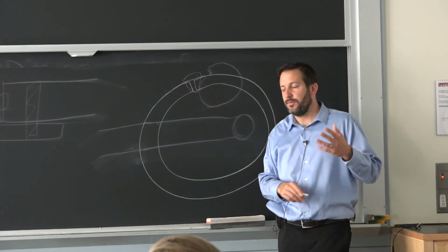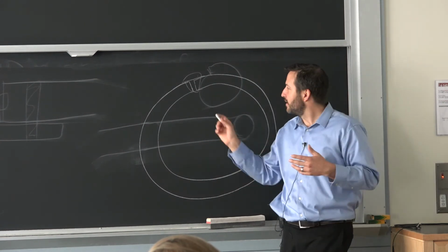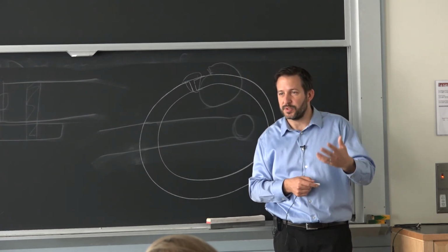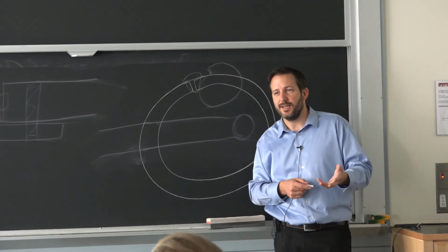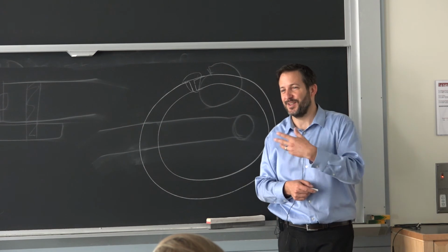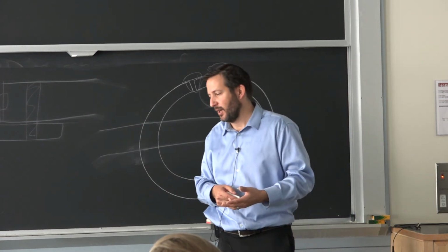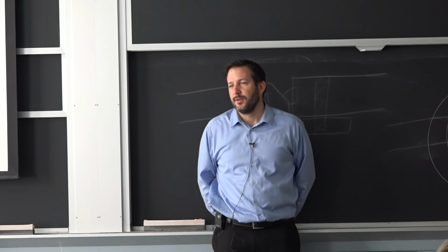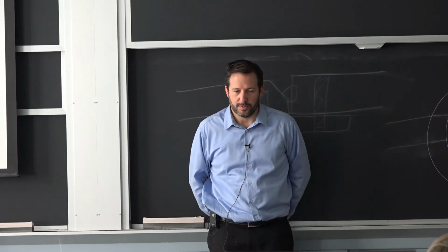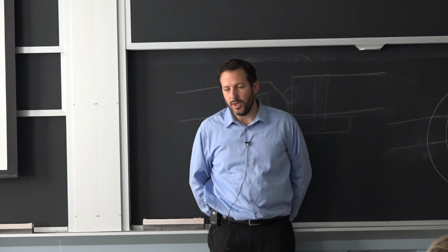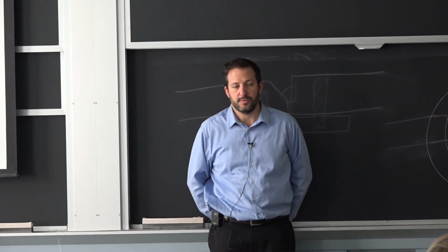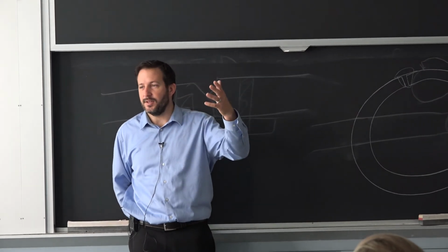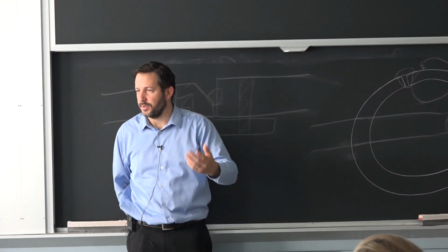And then we go through enough drawing operations that all this structure gets broken down back into the equivalent of a hot rolled material. So you have recrystallization, you have diffusion, and at the end of the day, you cannot tell that it was welded before. The same way that if you look at a bar of steel, you can't tell that it was ever melted, because now it has this wrought structure characteristic. So it's a very effective way, and it's used a lot with some very complex extrusion as well. So you do have essentially a fusion process, but it's so far ahead in the process of getting to your final shape that you can't see it anymore.